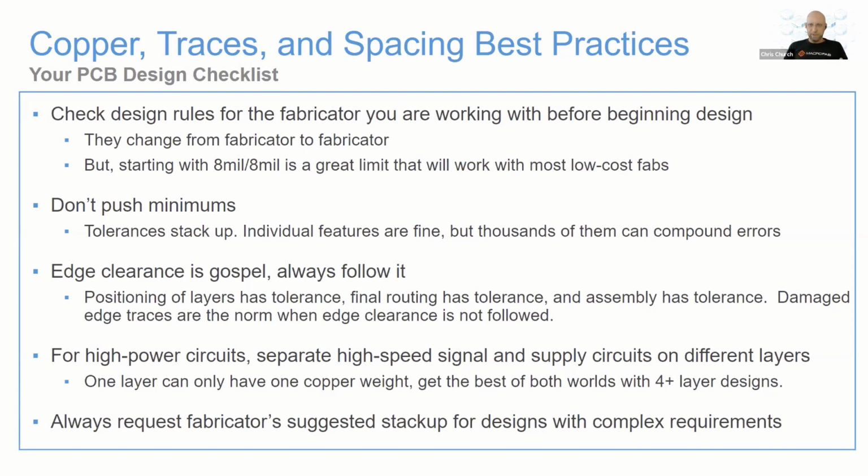For high power circuits, if possible, it'll help to reduce your cost and reduce your design constraints to separate the high power traces from the signal traces so that you can control the thickness of the copper independently. And then finally, always follow your fabricator's suggestions. They're telling you what they can do for a very good reason.